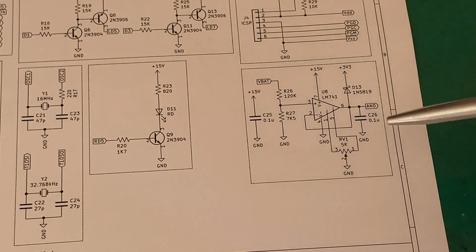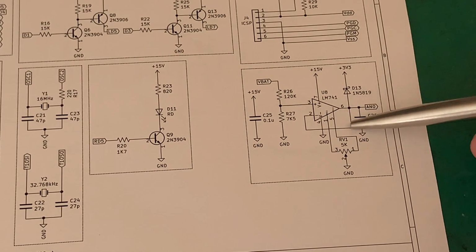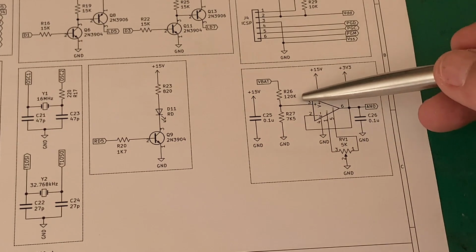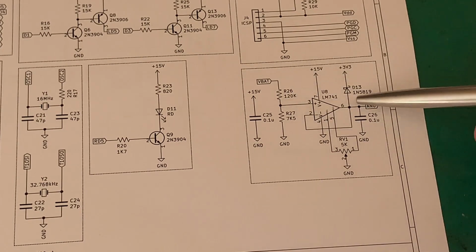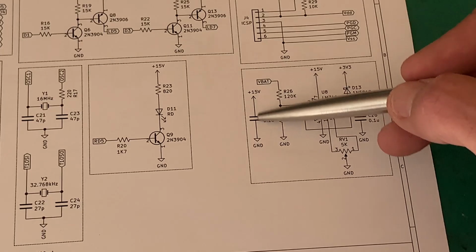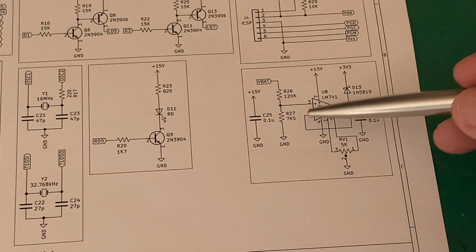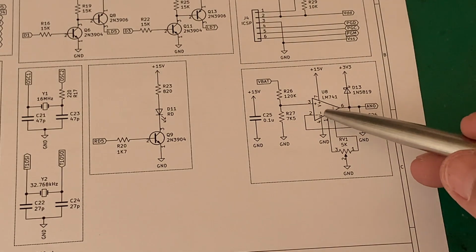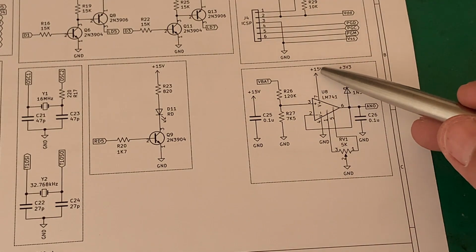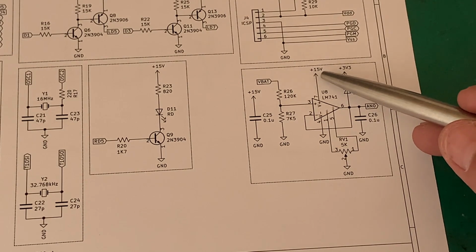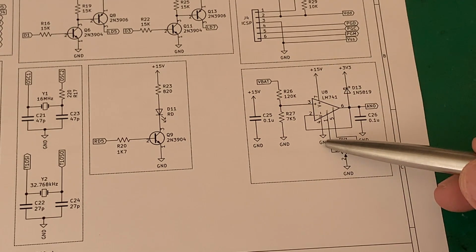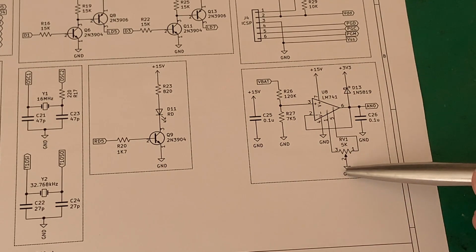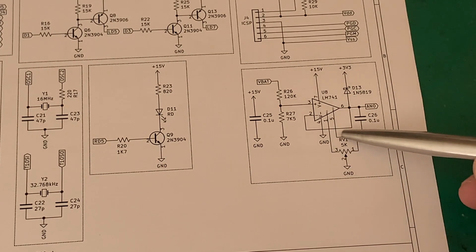So we've got our voltage divider, and simply put, we have our feedback on the inverting input. So what is this going to do as the voltage goes up? So will the output, in ratio to that voltage divider. As this voltage goes down, the output will go down. You'll see here I'm using the LM741. I'm powering it with the 15 volt rail plus and ground. I've got this little variable resistor in here to ground. This is for offset nulling.